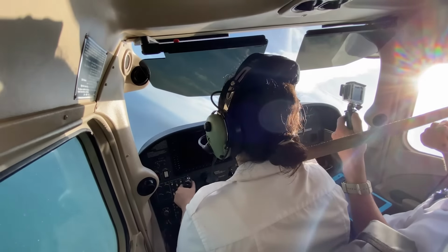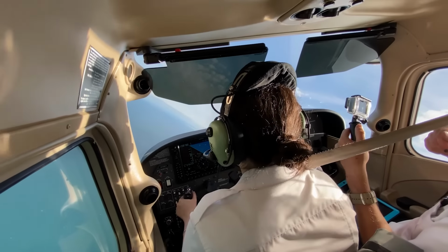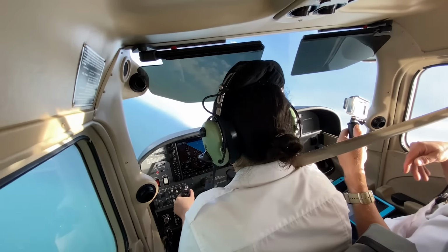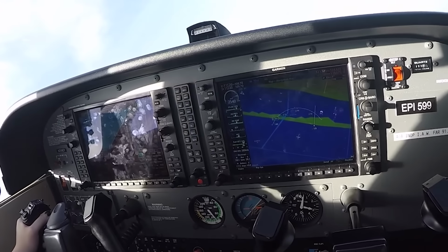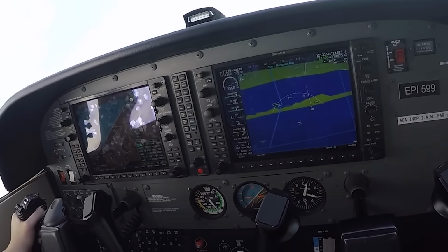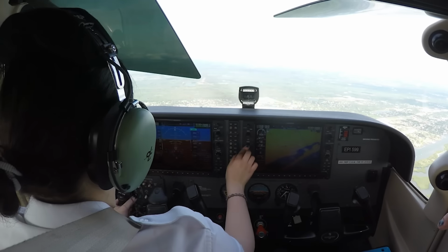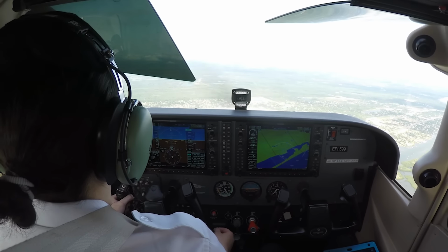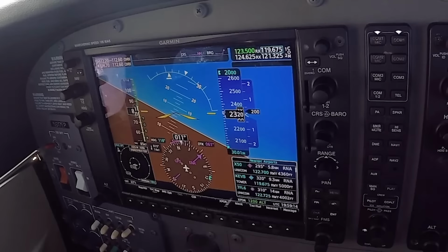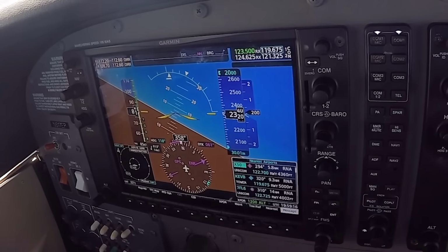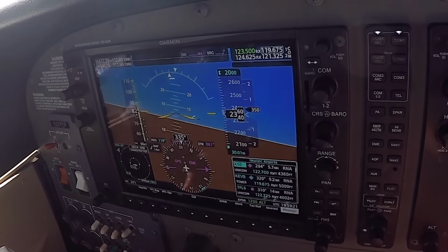The cockpit of an airplane is also called the flight deck. This is where the pilot controls the aircraft. The cockpit includes a seating area for the flight crew, flight instruments, avionics, audio and radio communications, and the flight controls. Electronic flight instruments include a multi-function display. This is used to control heading, determine your speed and altitude, as well as perform many other readings during flight. The primary flight display typically includes the attitude indicator, airspeed, heading, and vertical airspeed indicators.